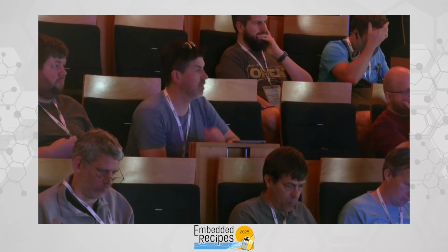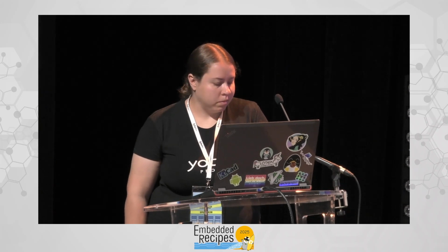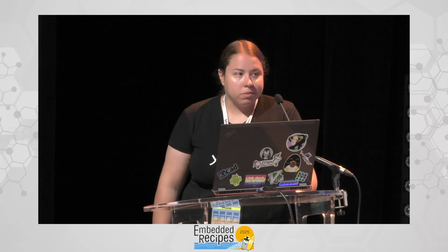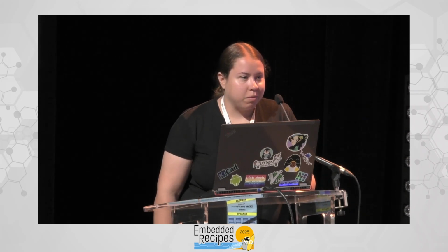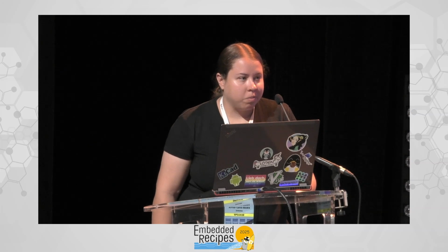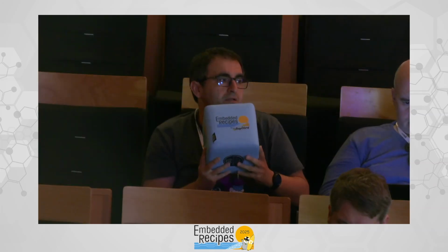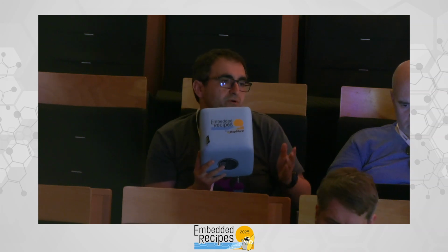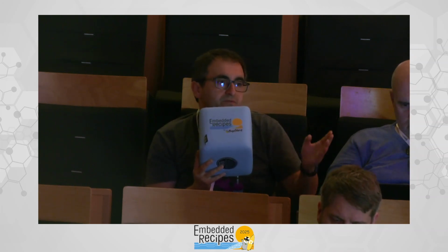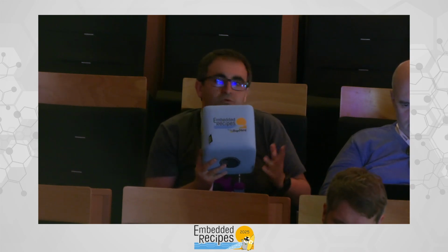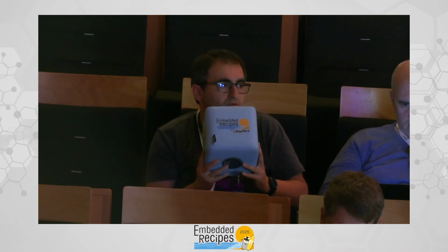One more question. Great talk, I've enjoyed it. Thank you very much. One of the things that I was facing is a problem I mentioned in a private conversation yesterday at the party with Anna-Lena. It's on boards like Raspberry Pi, where you don't have a built-in TPM, one of the options is to attach a TPM 2.0 over SPI, but obviously there are some risks involved due to the option for a man in the middle attack, someone to listen to the communication going on the SPI bus. Obviously, there is probably not a perfect solution, but what are the best practices to avoid this or to minimize the risks?